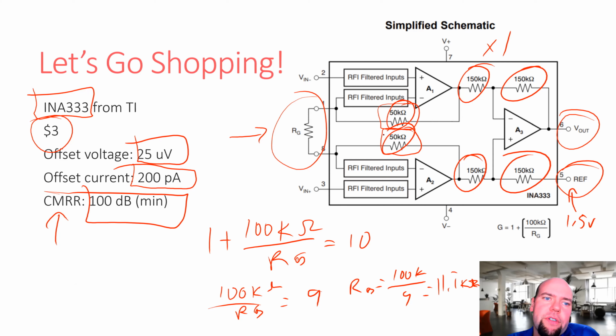We talked last time that for a gain of 100 op amp, which is even better, the CMRR to get 100 dB was something like 0.1% accurate resistors. So a big part of designing these types of amplifiers that you would buy from DigiKey or from Texas Instruments is internally having very accurate balanced resistors. And normally what that means is that they have a way of programming these. Internally, they usually have ways of compensating for temperature and controlling for process variation. So usually there's some way that they can tweak these things to get them nice and perfectly balanced once you actually buy them.